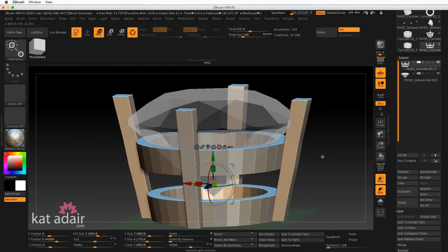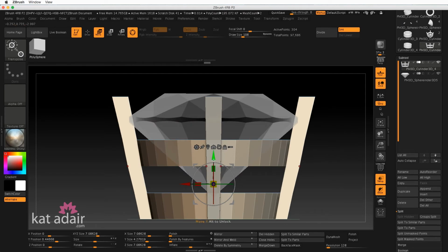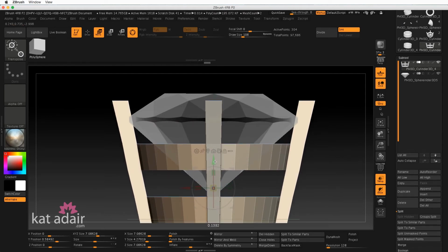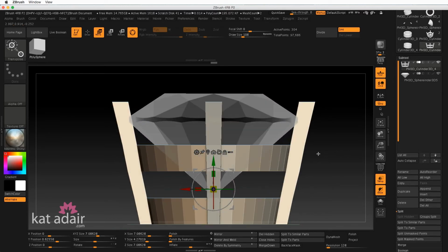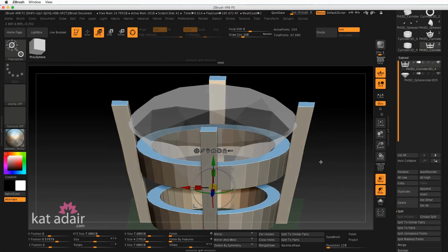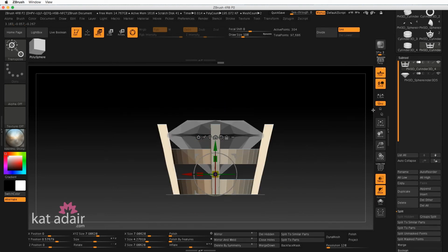So you can also see that the stone is interfering with the basket, so that might need to be a little bit less. I guess that collar we were just playing around with might need to be adjusted. Okay, so there it's not. If you're using a burr when you're setting it, of course, you may grind that out a little bit too. So you could do that. But let's just pretend for right now that this is close enough. It's close enough for what we're doing. So now it's resized to the point where we can turn off the stone, and let's focus on smoothing this out.